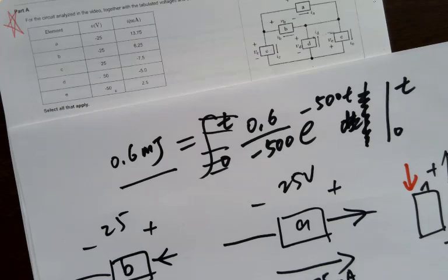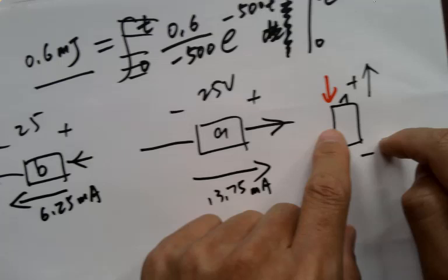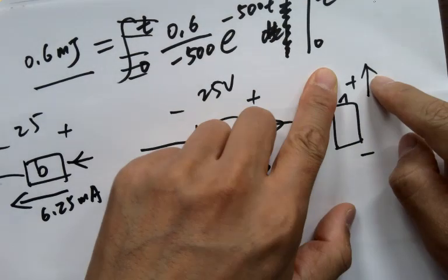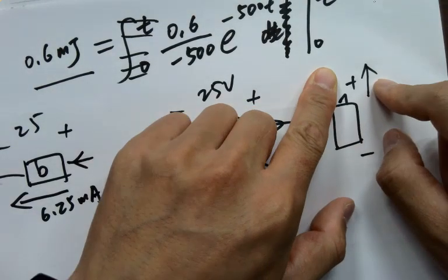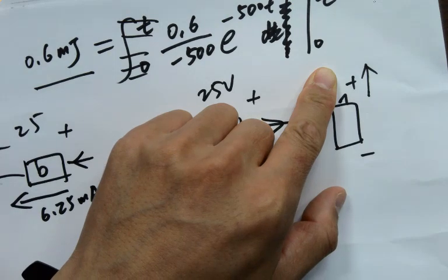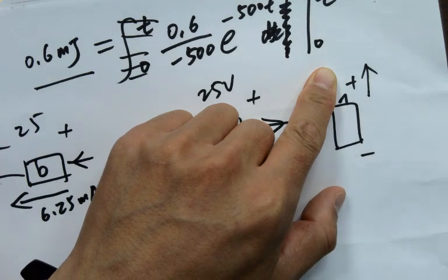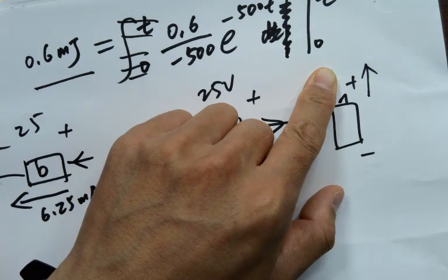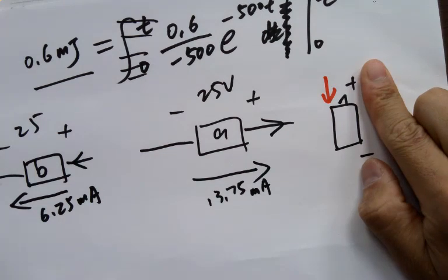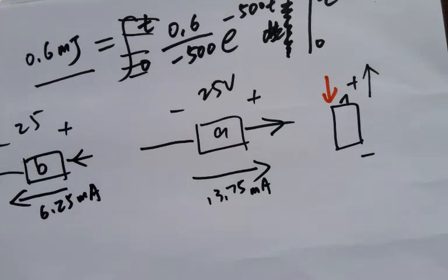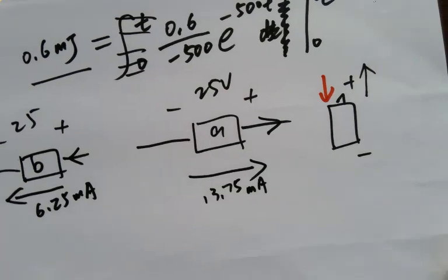Is that clear for this type of question? So for this one, you're getting negative or positive power? Negative power, right? In terms of this component, it's getting negative power because it's delivering power to the outside circuit, so just put a negative sign in front of it. For this case, it's a positive power. Then you have negative power and positive power for each component in the circuit, and you add them together, you're getting 0. So that's how you check the power balance of the circuit.